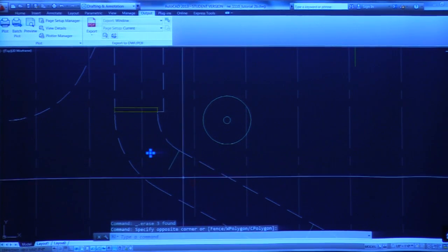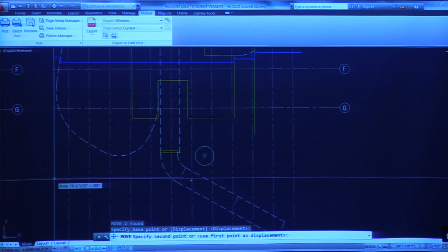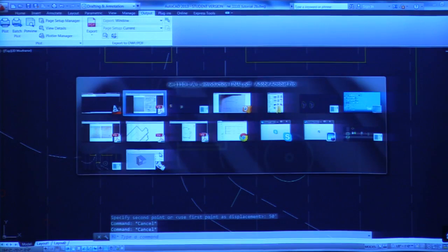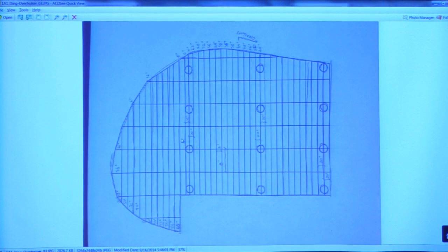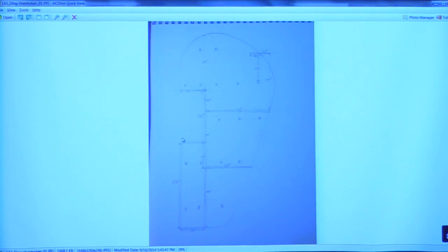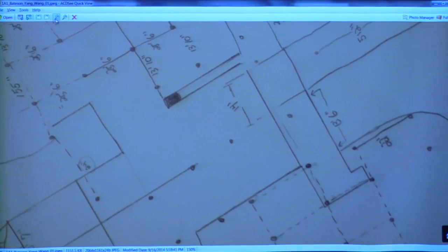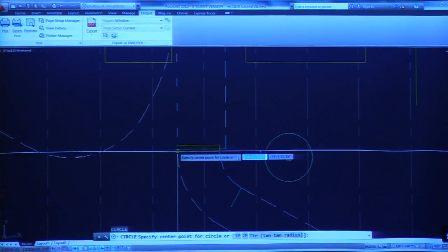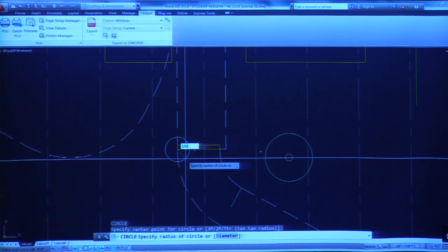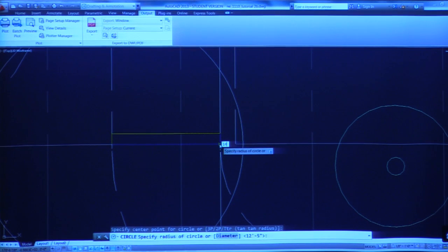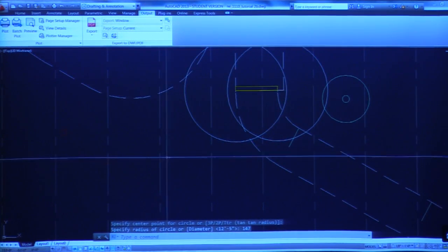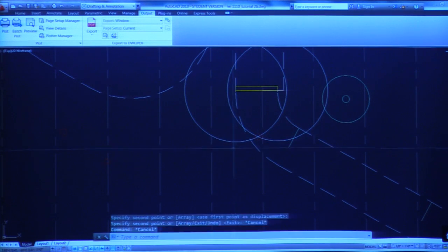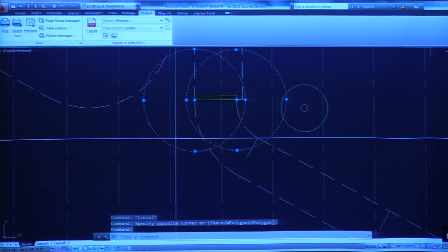So if I just move these guys 50 feet, and I go to my dimensions that I've collected here. So I have here 149 and 147, roughly, I think. If I make a circle here, that's 149, and I make a circle here, that's 147, I will get an intersection. So it doesn't agree with what I have there, but that's OK. I'm going to move that column to that intersection. So something might be a little off there, but that's OK.